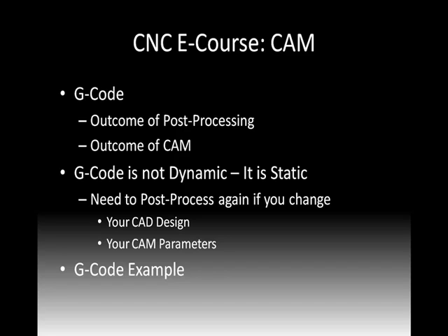Now, G-code is not dynamic, and let me explain that a little bit more. It's very static. Once you post-process and you have a G-code file, that file can only do one thing. It's a specific set of instructions. If you go back and change your CAD design and make it bigger, that G-code will no longer build the same part that you want it to. It's not flexible, it doesn't move with it.